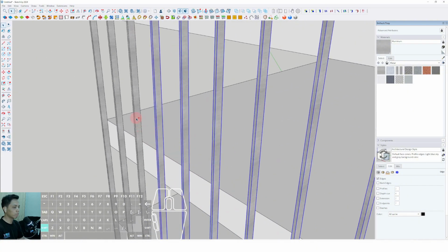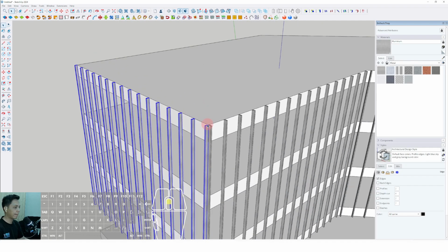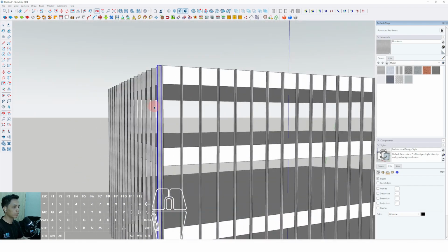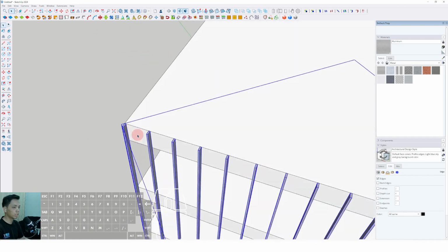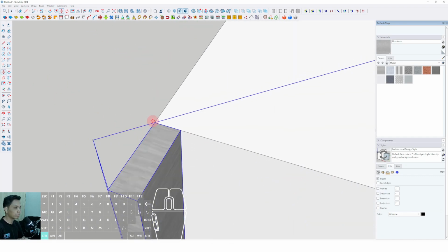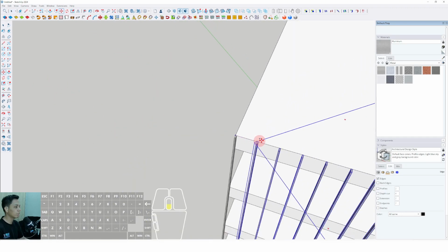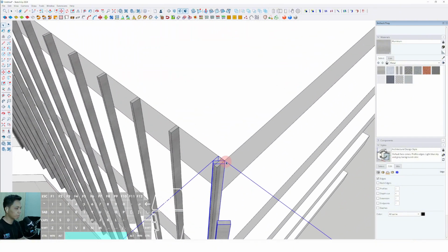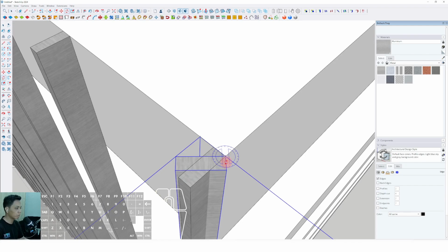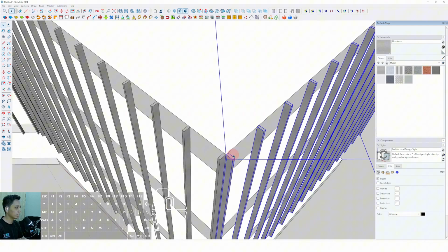We can select it all for this vertical frame. We have to select it all. Okay, we can right click and make group. Then we can select move. We can use the move tool, click from this point, then click to this other position. We can click to this position and rotate by following the orientation of this facade building.